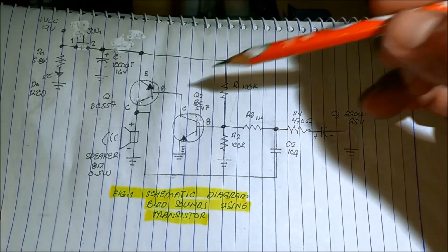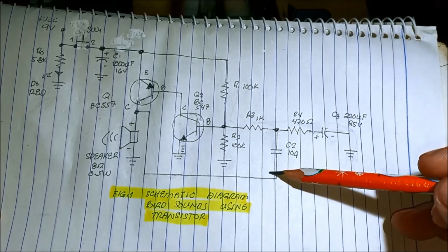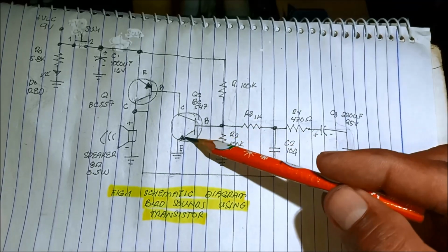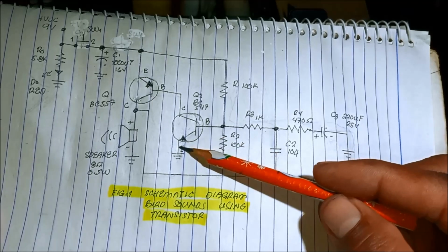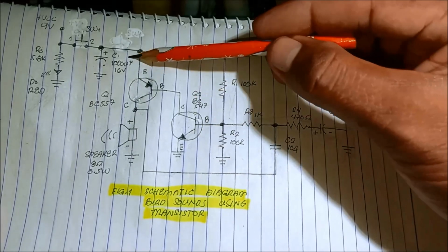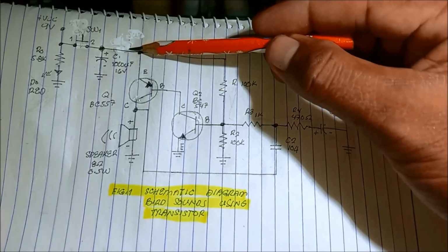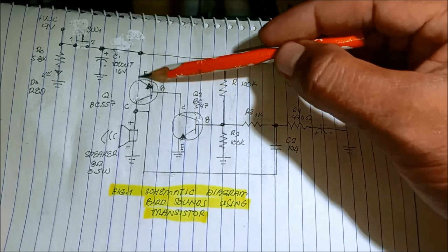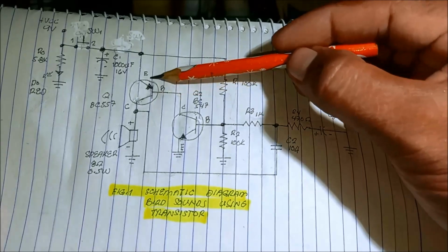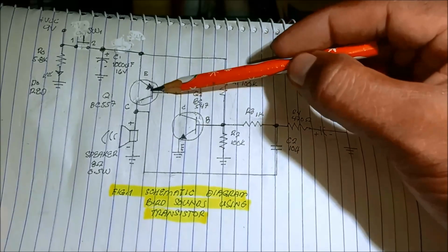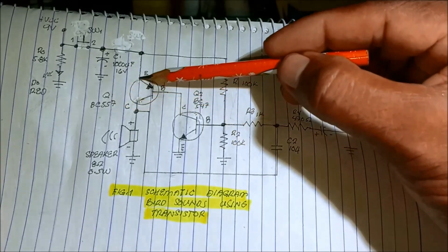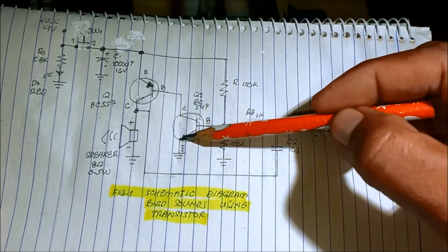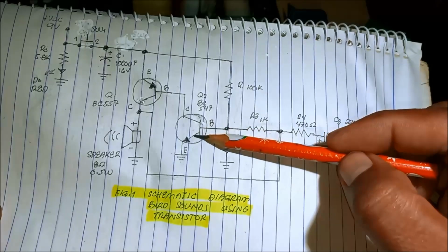And once the capacitor now is discharging, it discharges through the base of the first transistor. It will now turn on because there is a current that flows from emitter to the base. That is the current flow in the PNP type transistor. Current flows from emitter to base, then to the collector to the emitter, switching this transistor on.